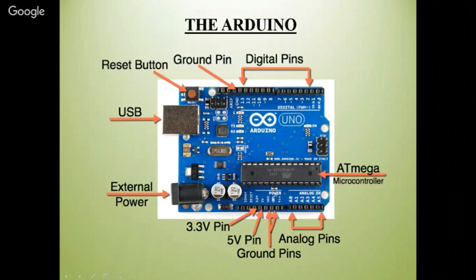And then the ground pins. There are 2 ground pins, and 1 ground pin beside digital pin 13. You can see 3 grounds are there. You can connect any one of them, as they are internally shorted. Then A0 to A5, 6 pins. These are the analog input pins. You can take analog signals like LDR signals, for example if you want to make an automatic smart light. Analog pins A0 to A5 can take 6 analog signals simultaneously.